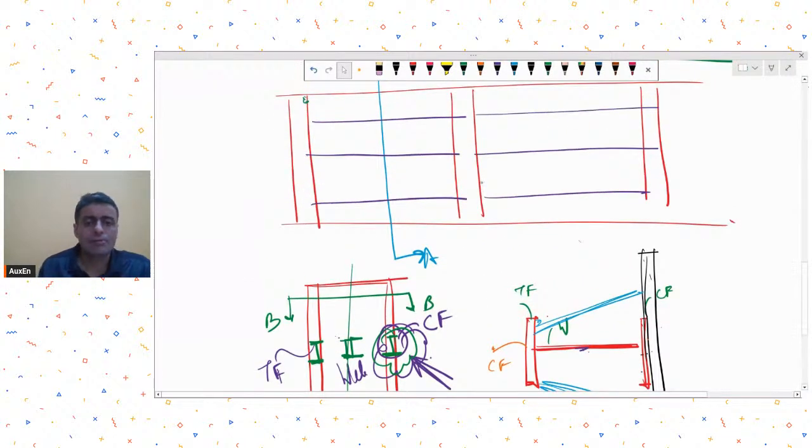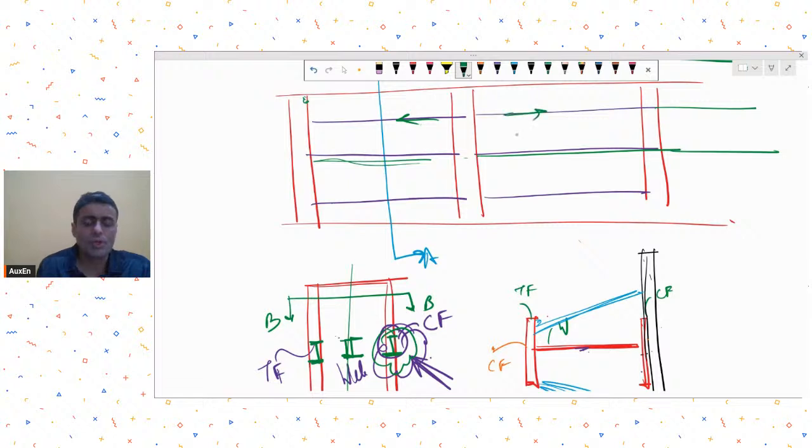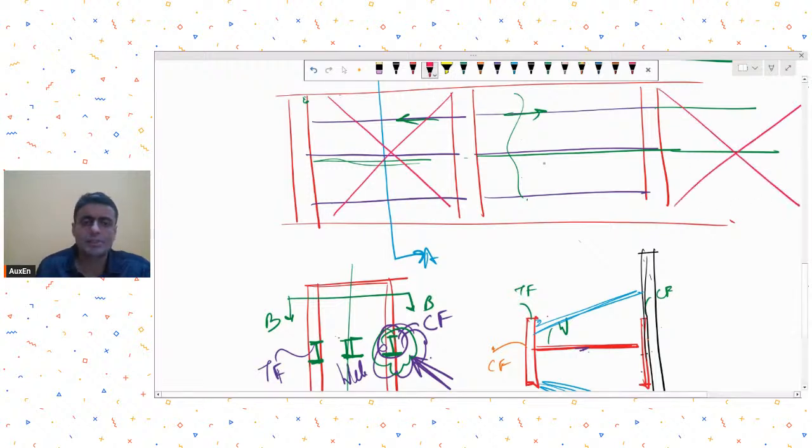See, it will cause, but please remember that it is also being carried forward to the other members. So whatever push and pull is happening, that is also happening on the other side. So it's rare that this will cause any eccentricity or plan torsion. And also remember that for that we usually have a bracing-like system also.